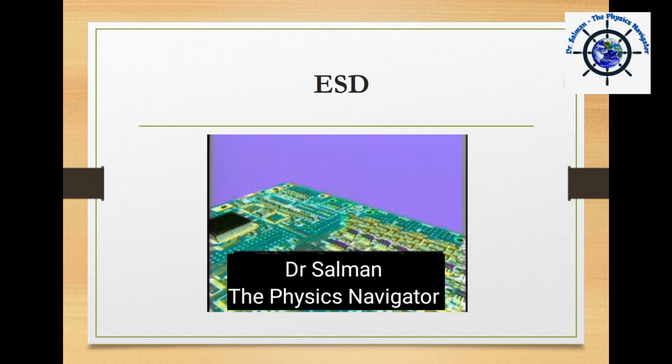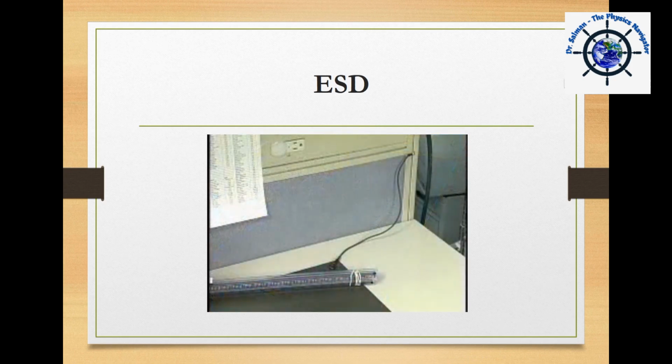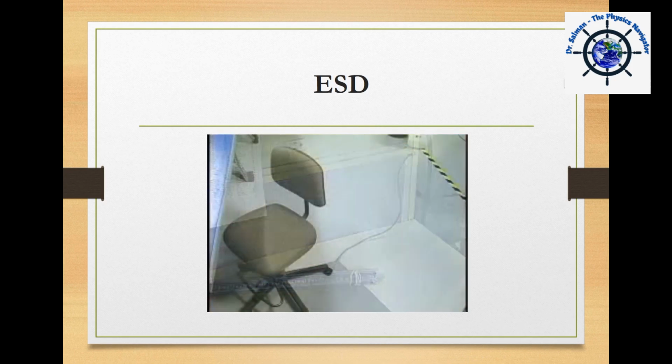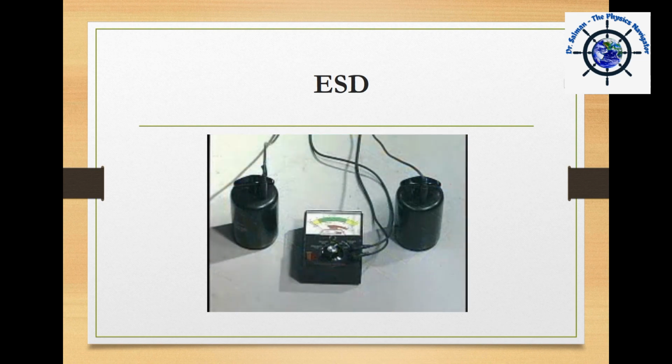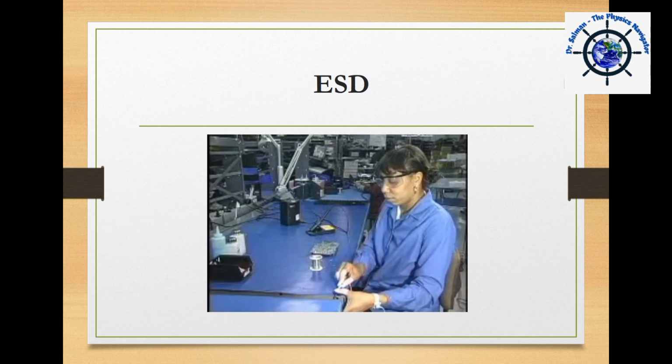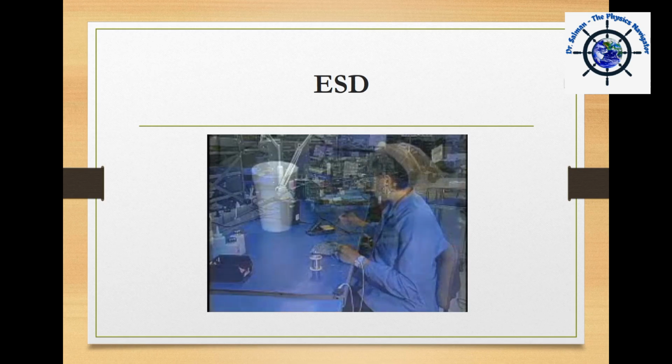since the rapid transfer of a charge to a conductive surface may cause damage. The material used to eliminate those harmful discharges is called static dissipative and may be found in various work surfaces, floors, and containers. These materials conduct electricity, but do it slowly enough to leave the ESD-sensitive device undamaged.